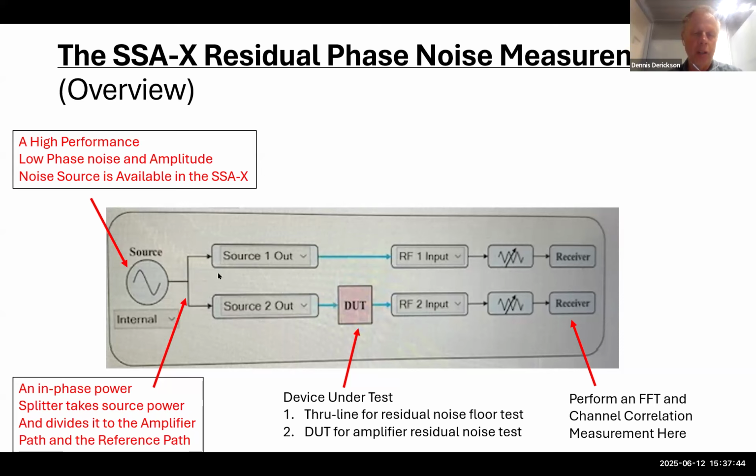We're going to split it into two, and so whatever non-perfection this source has, this will add a little bit more non-perfection. But here we have an asymmetry between the two channels. We've got this channel without the DUT and a channel with the DUT. So at the output, you're going to get just the source noise plus this channel noise. You get the source noise plus channel noise here, but you get this additional noise called the DUT noise. And that's what we're trying to characterize. Here's what we're trying to get: how much additional noise does the device under test add?